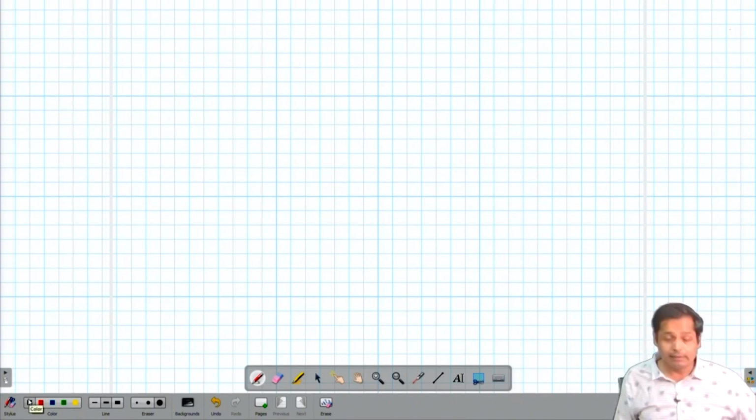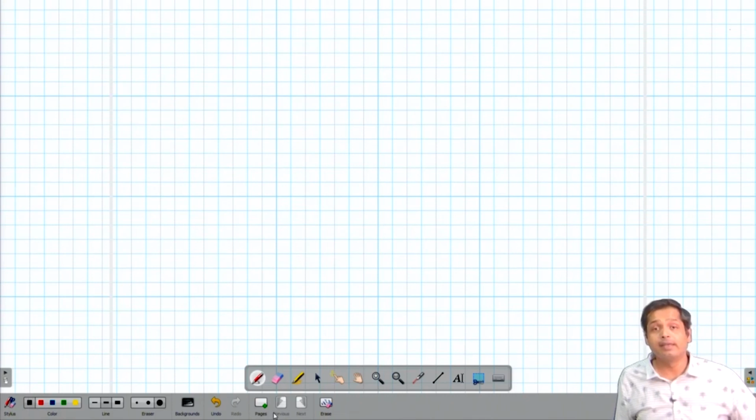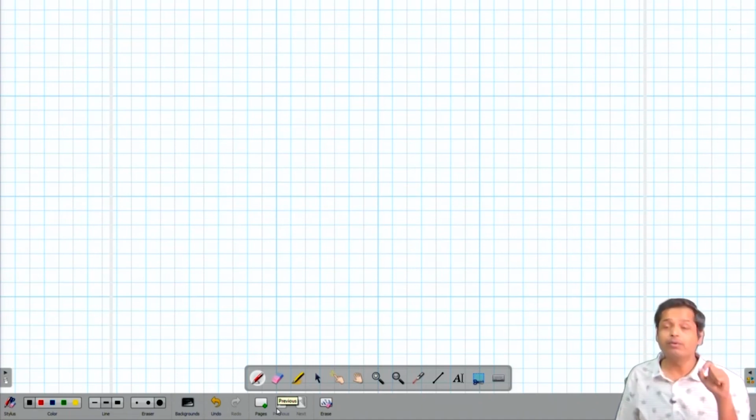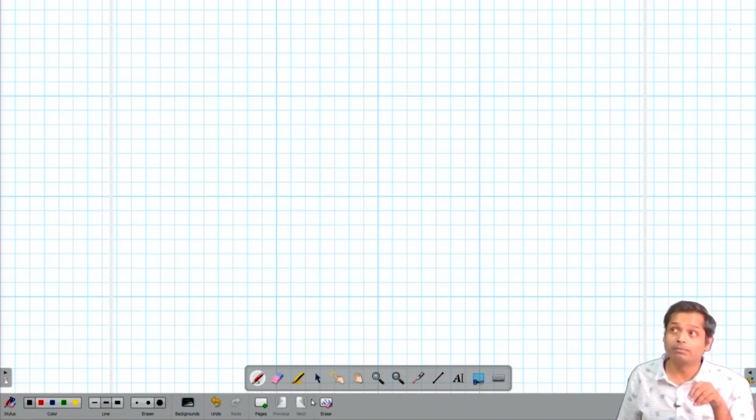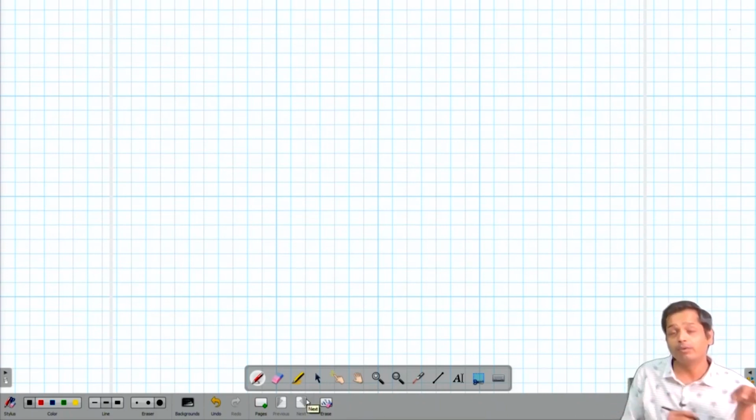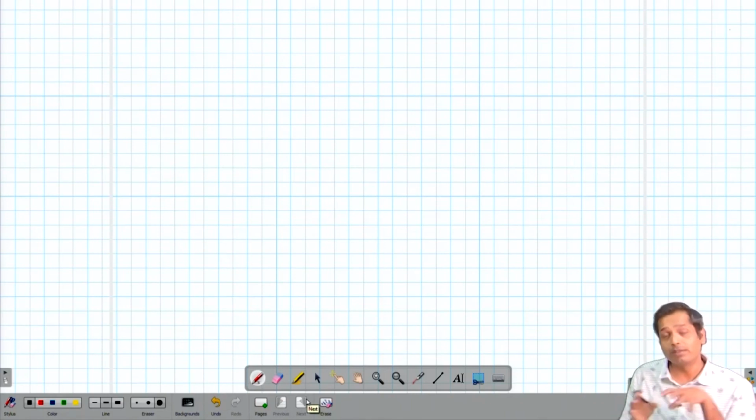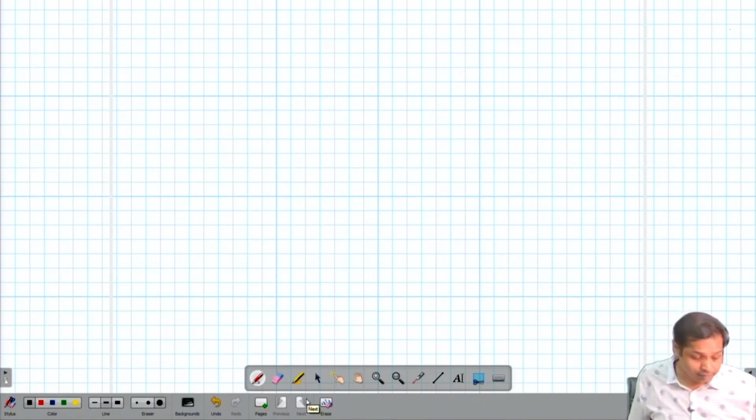Okay, another interesting thing is if you see the equation, that equation involves derivatives, right? Now we know how to transform xi, eta to get the corresponding x, y. We also need to know how to map the derivatives with respect to different coordinate systems.